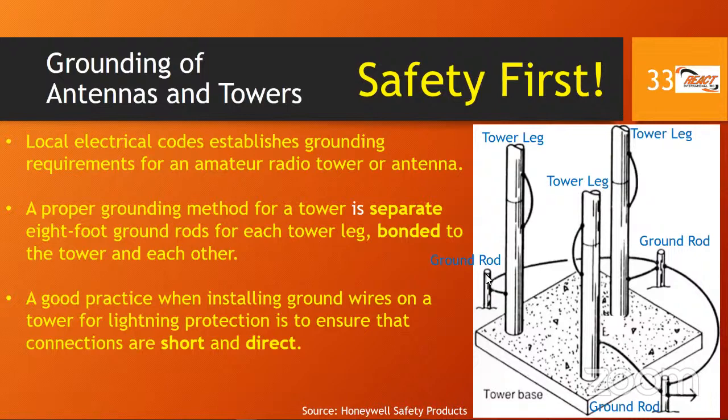This is an 8-foot ground rod that's driven into the ground. Another 8-foot ground rod that's driven all the way into the ground. We just have a couple inches above. So these are ground rods into the earth. And notice that for each of the legs of the tower, we have a ground rod, and the ground rod is connected to the leg. But you may also notice that the ground rods are also connected to each other.